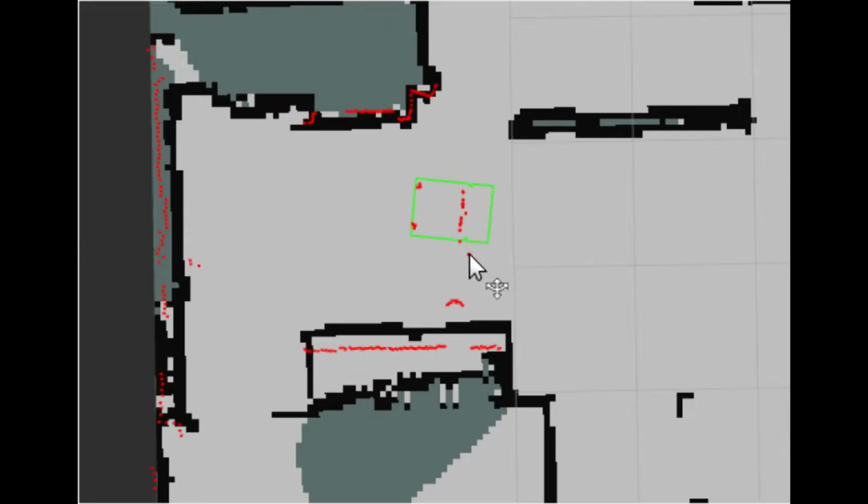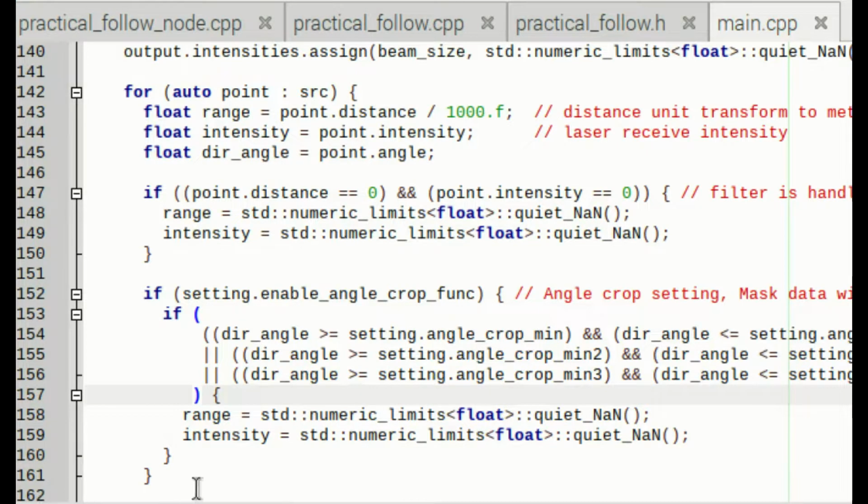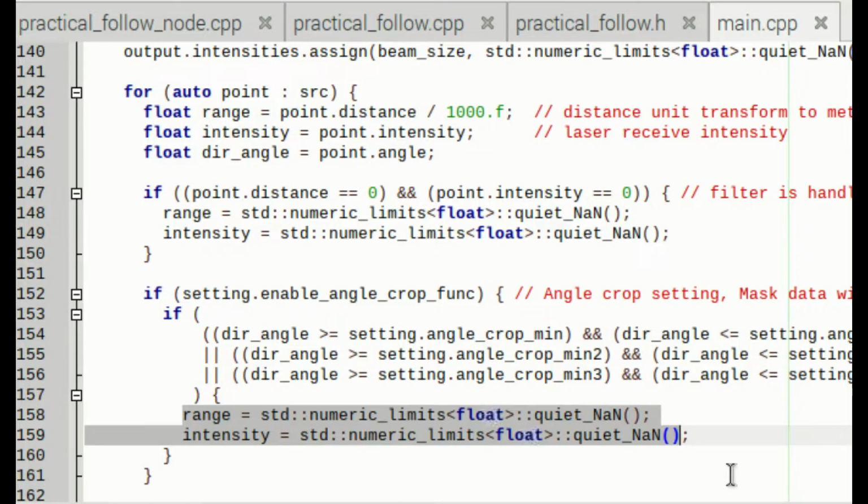And sometimes when the beam is skimming the very edge of these obstructions that are within the robot's footprint, it will plot out a little phantom obstacle several feet away, and that messes with navigation. Because I understand that a laser scan is just an array or vector of elements, I was able to add 2 little lines in the LiDAR's ROS driver that cuts out my angle as well as the original. It took me just a couple minutes to do, and it has saved me a lot of headache.